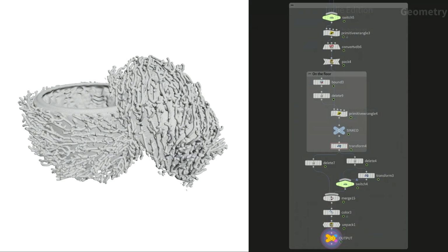Once the union was complete, I converted it back to a polygon so that I'd be able to print it in 3D printing machines. I also made sure that everything is connected. You see some virtual objects floating around. I just deleted all those floating objects and made sure everything is in one shape.